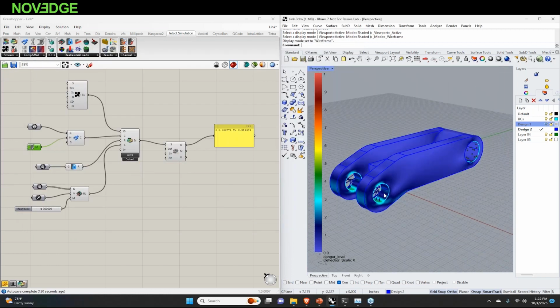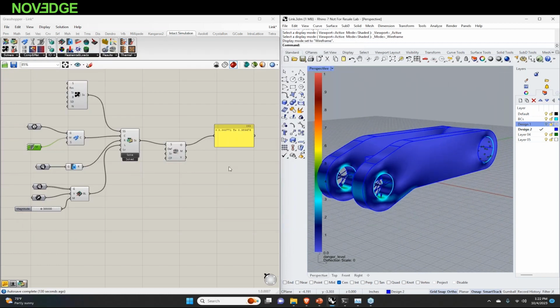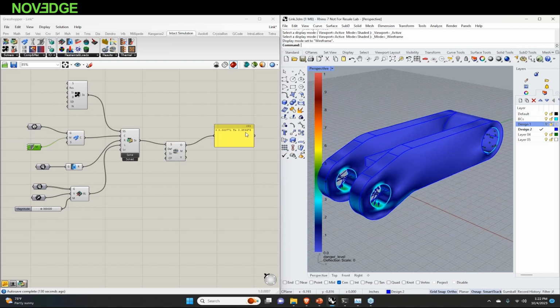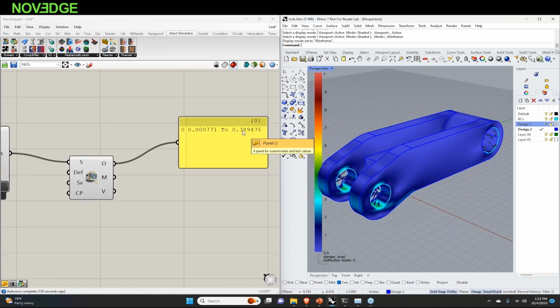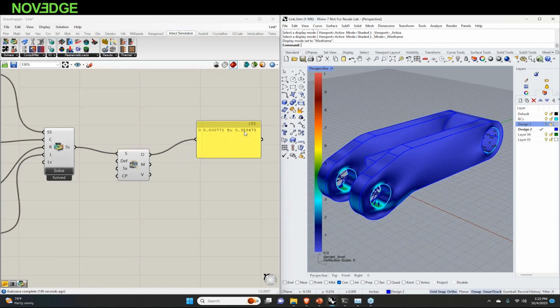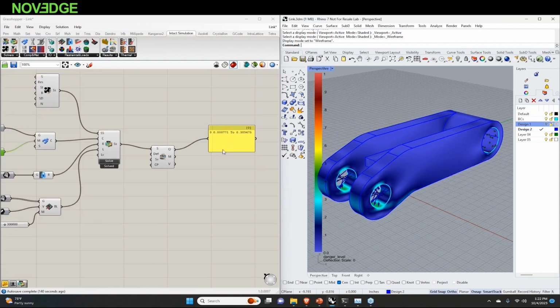And we've got new results using the new material. Now, you can see here the danger level has been reduced to 0.38. So it's been reduced by about 60% just by choosing that better material. And we could probably use the original design using this material as well. But in this particular case, this geometry is actually smaller, has less volume, so it actually uses less material.